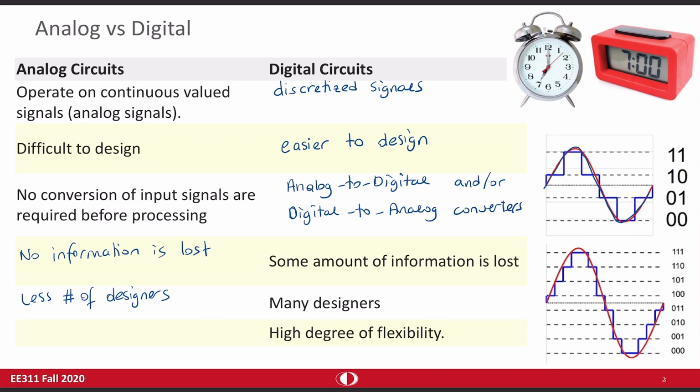But for analog design, of course, this is a significant thing because when the voltage changes because of the losses, let's say, it may change the operation region of the transistor and it may result in malfunction of the whole system. So analog circuits are not that flexible.